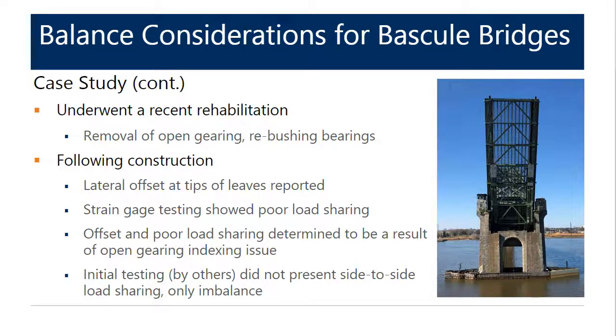Initial testing was performed by others. However, the results did not present side-to-side load sharing. They only presented total imbalance of the bridge. This highlights the importance of owners and contractors to really understand what they are asking for when they request strain gauge testing to be performed. Strain gauge testing does provide imbalance, however, it also provides a lot of information about load sharing and machinery loading in general.